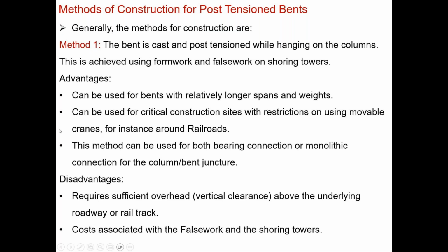I would say this method of construction works for either a bearing connection or a monolithic connection for the column-bent juncture. So that provides a big advantage for those straddle bents, to be able to design them either way, with a bearing connection or a monolithic connection.